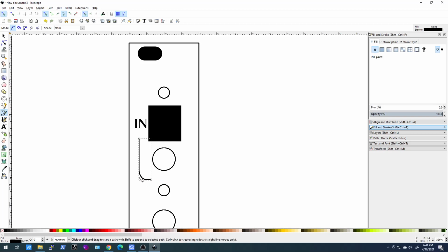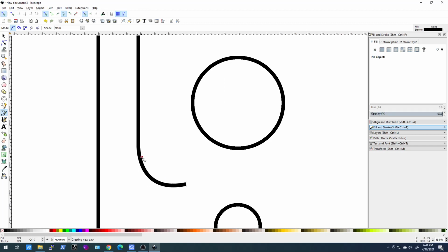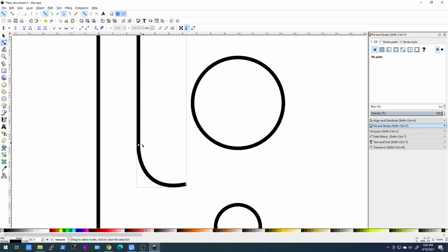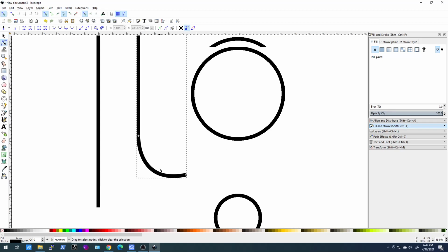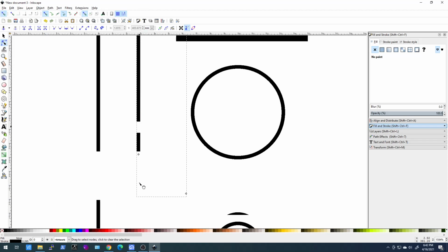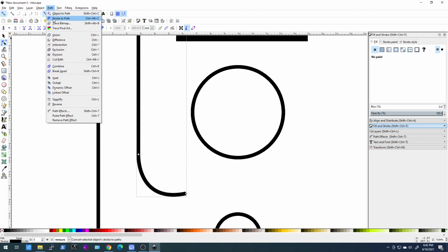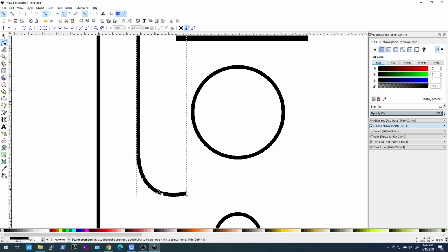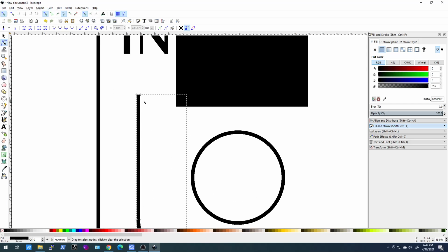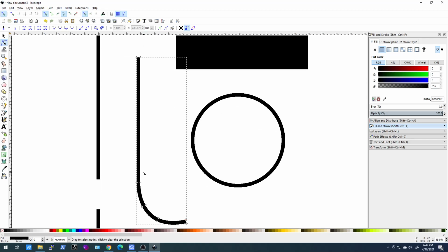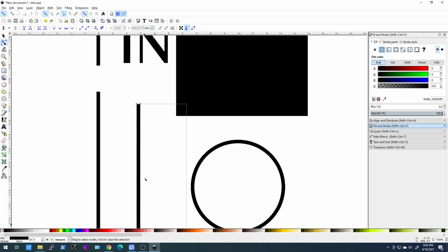Alright, so now we've got a basic line. You might say, oh, well, that's a path, so we can import it. And we could import it as a trace, but we can't import it as an SVG, like a graphic type design thing. So let's click on it. We'll see at the bottom it is a path, but if we hit the node tool, we only have middle nodes. So this is not going to import the way I want into EasyEDA. To fix that, we'll go up here to path, and then we'll do stroke to path. Now you'll notice all these nodes pop up, and that's telling us that we now have a region that we can import easily into EasyEDA.